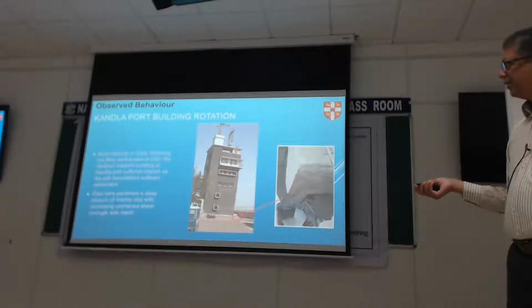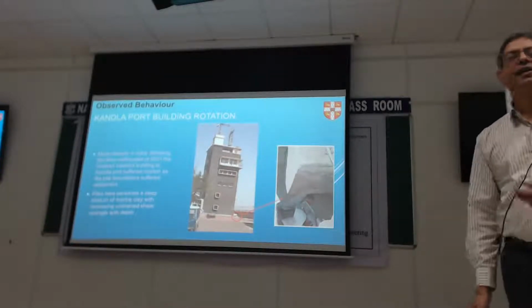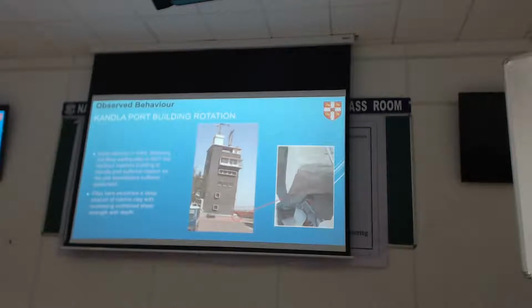The soil conditions in Kandla Port are such that you've got soft marine clay on the top, and there's no bedrock. The clay gets stiffer and stiffer as you go deeper, but you'll never reach the bedrock. Bedrock is some 150 meters below. No pile can go that long.